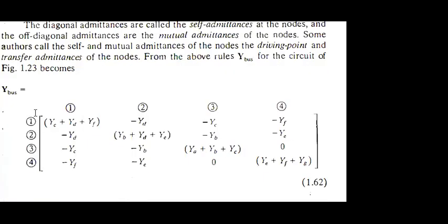So this is the summary. When you complete all the nodal equations, the equation will be something like that, right? This is the final version of all the y, and that is known as the y bus matrix. That means the coefficients of all the admittances in matrix orientation. From that chart I can say what is the coefficient of the second, third or fourth equation.